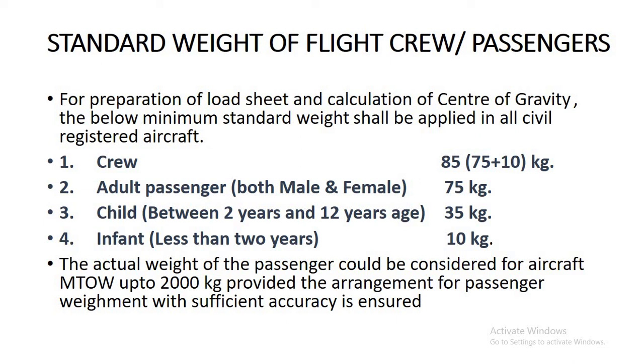And if you have an aircraft less than 2000 kg MTOW, and only a few passengers are carried, then you can use the actual weight if you can accurately calculate it, instead of using the standard weight data.